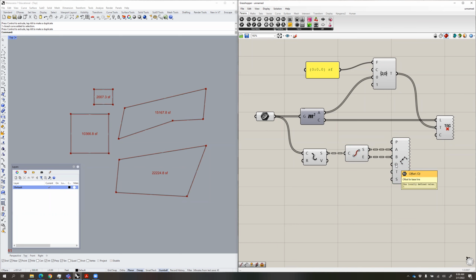There's an offset from the baseline. So how much do you want this dimension to extend off of that? Right now it's offsetting by a unit of 1. Maybe you want that to be a little bit bigger. So what I'm going to do is to adjust this value here. You can either put in a little panel. I'll just do that. Let's bring in a panel. Actually, I'll do this instead. Instead of using a panel, I'll use another tool that is worth